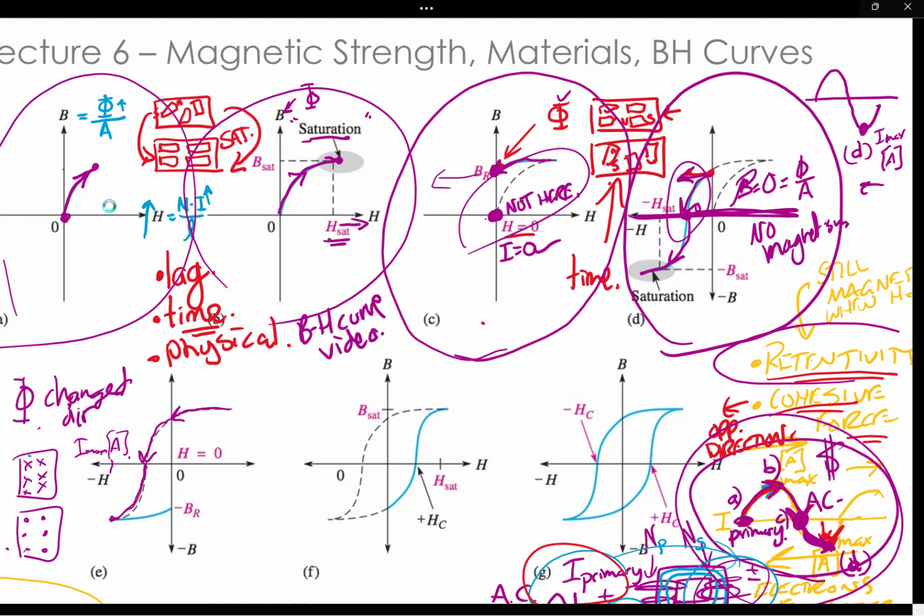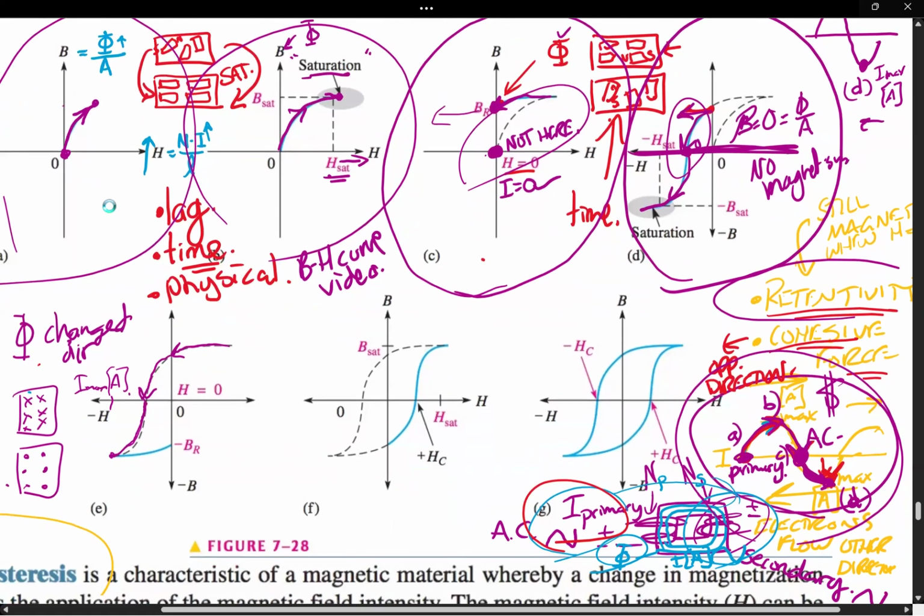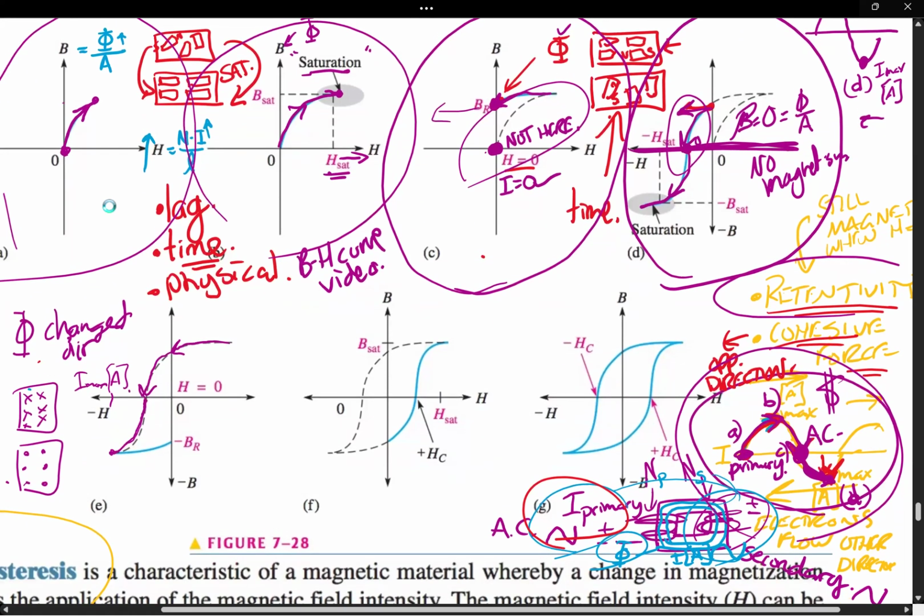They change direction as well. So the magnetic flux is constantly changing. In order for the magnetic flux to be constantly changing, we're into Faraday's law, Faraday's principle, and you should really review the video on Faraday's law. Faraday's principle is really important here, because Faraday's law says if there is a changing magnetic flux, then there's a changing induced current, and that's how we get our current in the secondary winding of that transformer.